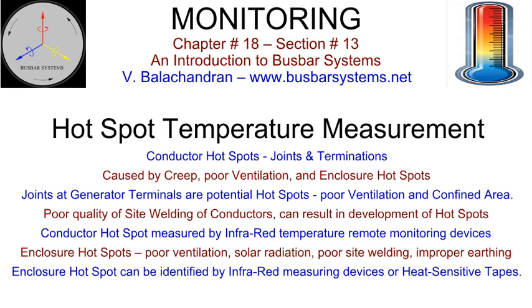Poor quality of site welding of conductors can result in the development of hotspots in that location. Conductor temperature at hotspots can be monitored by installing infrared temperature remote monitoring devices at strategic locations.